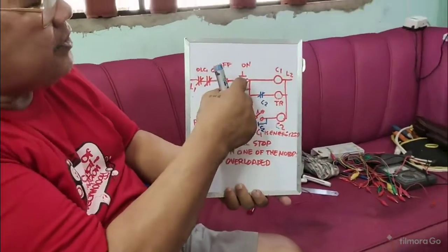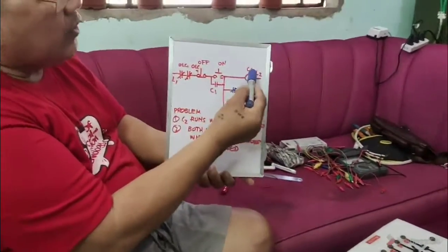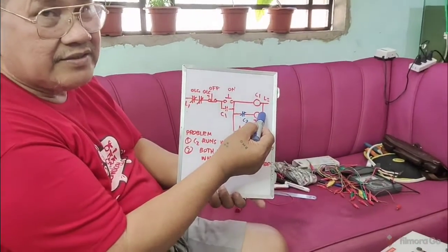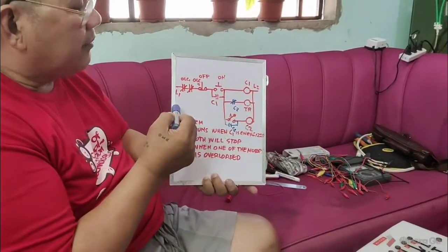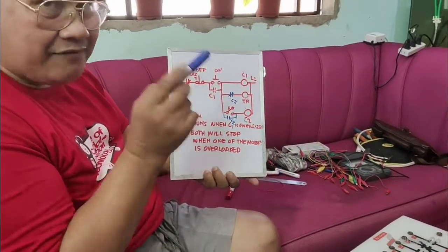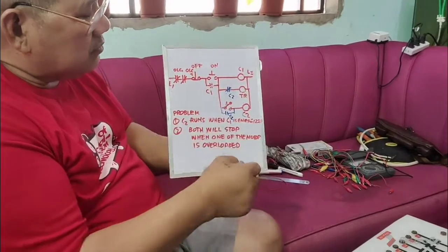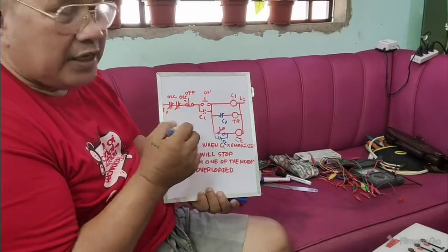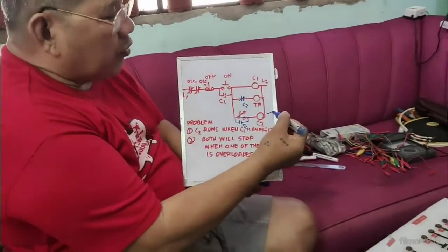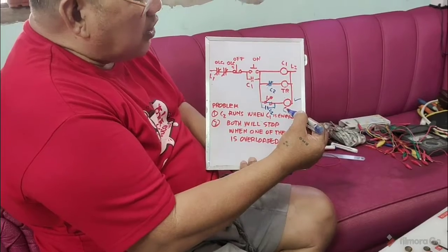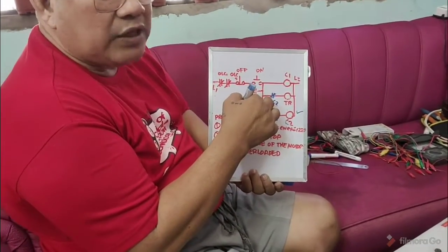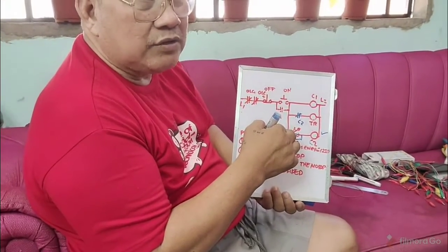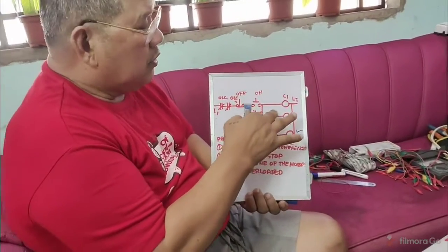So again, I will press the button here. This one is energized. This will close. Okay? And this will also energize the holding coil of the timer. After a few seconds, the timing contact here will turn on, energizing conveyor 2. When conveyor 2 is energized, of course, what will happen to the auxiliary contact connected in series with the time delay relay holding coil? This will also open.